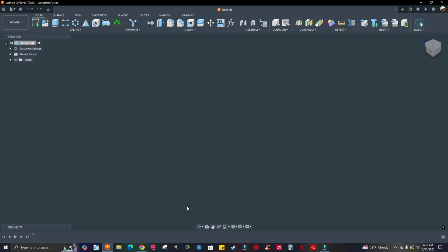downloading, just getting a copy of the tool library, your Homag or Weeke tool library, and converting that file into a Fusion file, which can be, I think it's three file types. I think it's JSON, the other one CSV, and then the other one's HSM. Okay, but for me, it was hard to convert. I couldn't do it, so I just manually added every single tool that I have for that Weeke. I just added every single tool into Fusion. Okay, so let me show you how I did it.